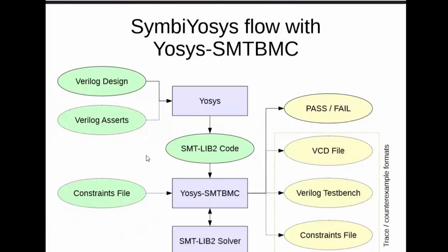So let's say it's a very deep proof and it ran for 100 cycles. Then you can just use the first 80 cycles or whatever from this constraint file and see if in that state space the solver will find another bug or the same bug again, and only after that succeeded, you just run the unconstrained proof again.